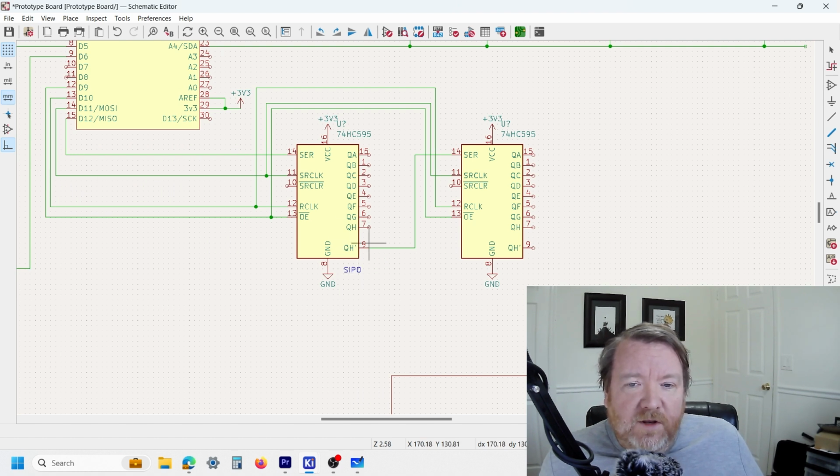If you wanted to look at this in reverse, there is a 74HC595, I believe, which is a PISO, parallel input serial output, which basically does the reverse of this. It takes digital signals in on one side, then with the clock pulse it converts that back into serial data, which you can then read back in through 3 wires. Okay, so with that, I'm going to finish the KiCad part and switch over to a demo.